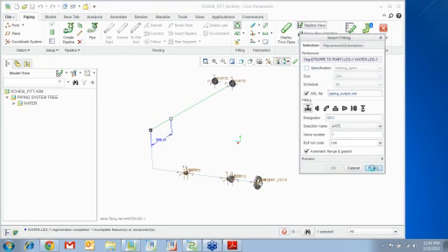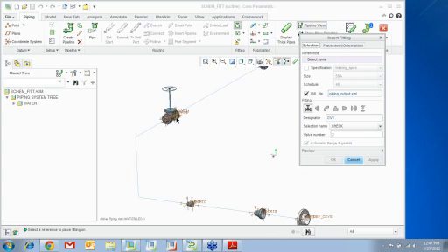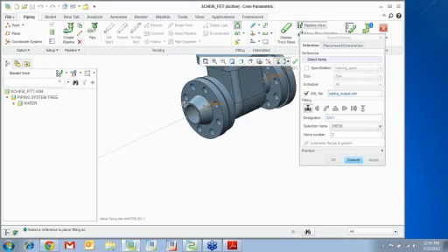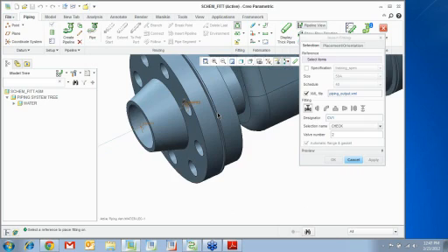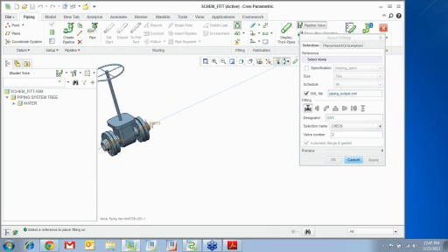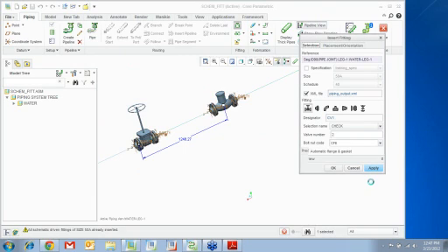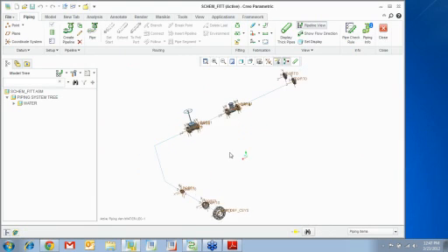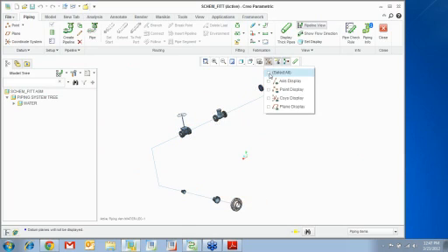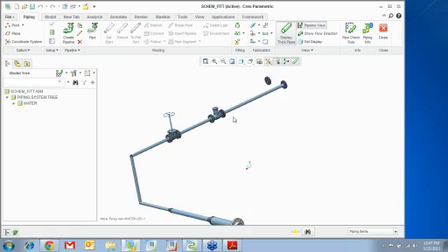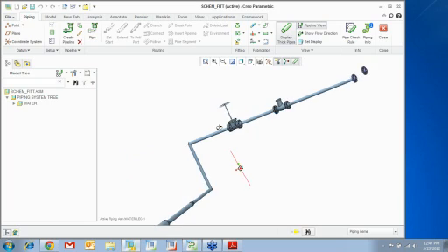You hit apply. Notice automatic flange and gaskets are added. So you can see the gasket and the flanges. You want to go pick next and you see check valve. There you have it, it reads from the schematic, gets all the sizes. All you do is pick and place and choose a location along the pipeline that you routed as to where you want to place this. That's all you pretty much do. Other than that, everything's done through the schematic.